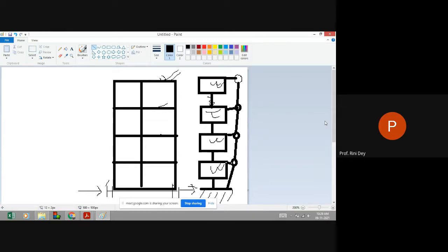So the technique of evaluating the natural frequency: look here, we do not calculate each mass separately. See, these masses are connected to each and every mass along with it, isn't it? So this mass is attached to one mass. So the inertial property will definitely get attached to another mass as well. Similarly, that mass's inertial property and the stiffness coefficients are also attached with the other masses. So these are the things which we have to consider, because the mass will not only move with its inertial property by its own, because it is also attached with the other lumped masses as well.